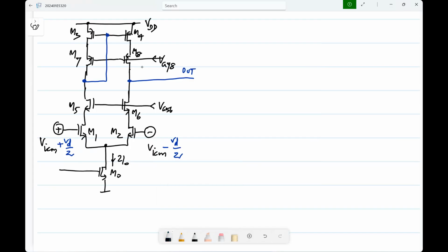Now, what are all the things that will be different between this and the conventional single stage op amp, that is, without the common gate buffers or without the cascodes? Gain, clearly, that's the main purpose for using this, and the output resistance is higher in this case, right?